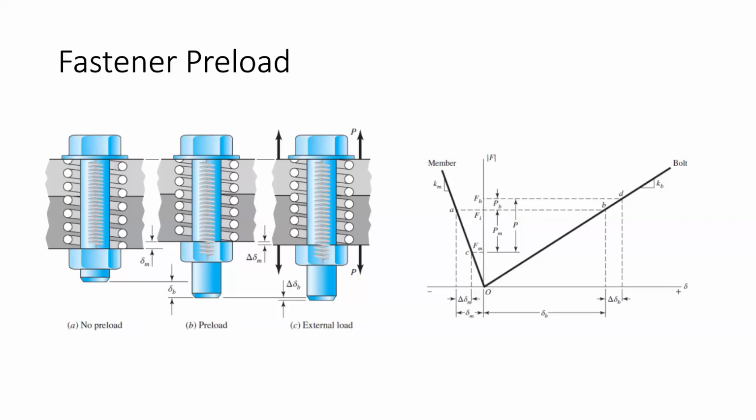But this is an example of where fastener preload can really change the way that you approach the system. Let's say I didn't torque this fastener down much. If I were to pull these two plates apart, they would basically just shear the bolt interface. But the interesting thing is that you can actually preload these screws a lot and clamp the plates together. Now you have another way to react that shear load, and it's the friction between the two plates themselves. If I preloaded it enough that the friction is enough to resist the shear force, then my fastener no longer ever gets loaded in shear.